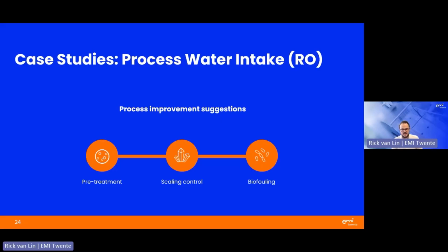And since there was a granulated active carbon pre-treatment, disinfect downstream of this active carbon. So use UV or MF or UF, as this granulated active carbon can become a biofilm nursery. And this tight media filtration might help mitigate the bioload.